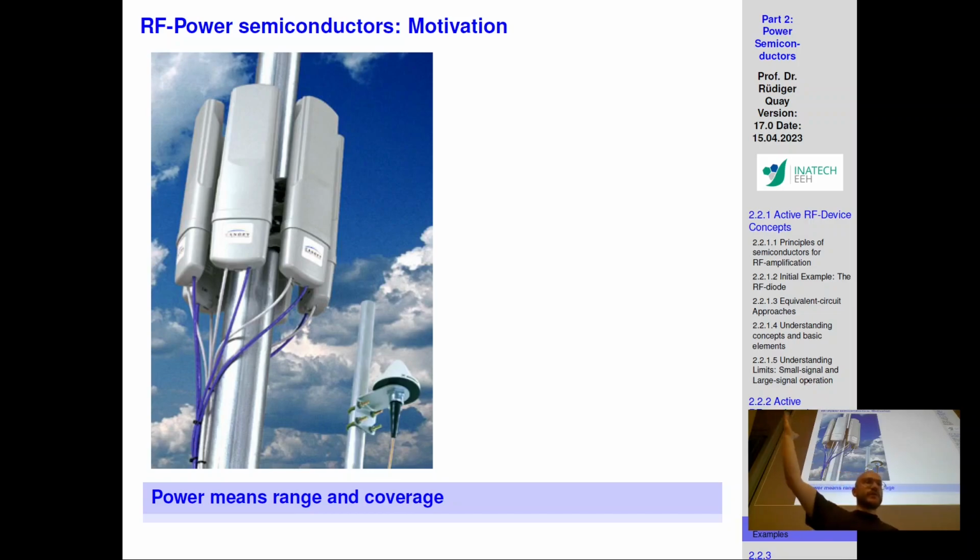An amplifier will not amplify to infinity. A horn antenna will transmit any frequency from a lower cutoff upwards, but an antenna won't be able to transmit anything if the power amplifier doesn't generate the signal for it. And a power amplifier obviously acts as a bandpass as well, meaning that even if you have a source that theoretically could supply you with a low powered signal for higher frequencies, if the power amplifier itself reaches its FT, or its Fmax, then you will not be able to send any signal out. And thus, power devices are very important.